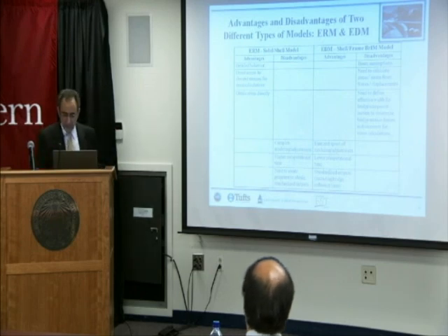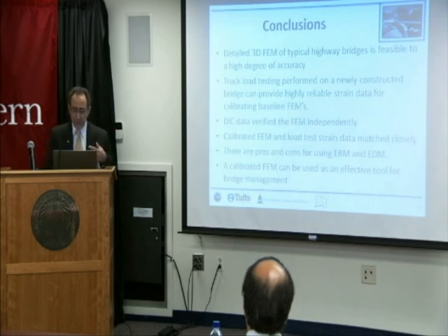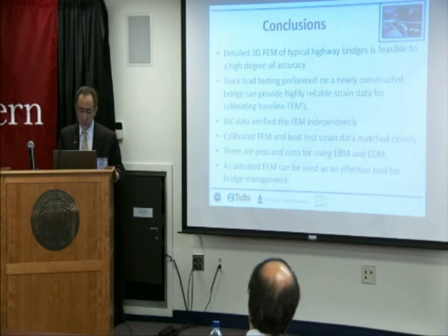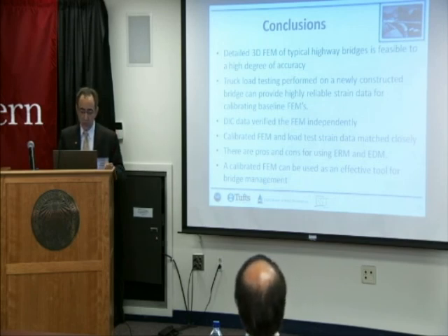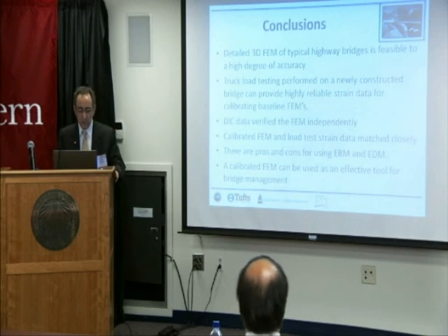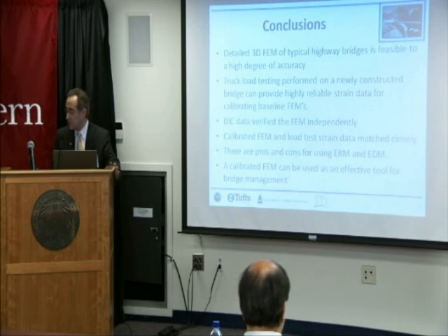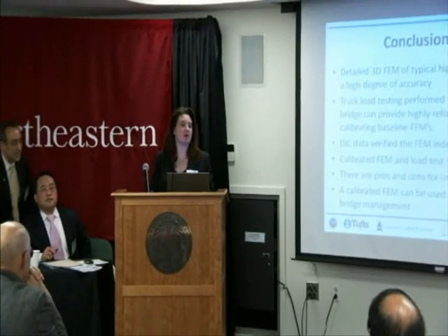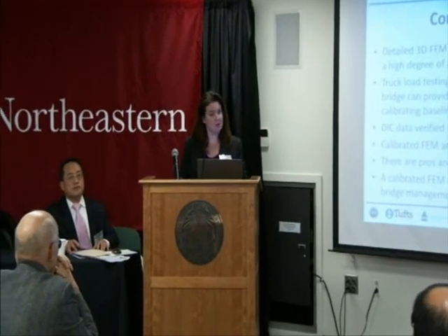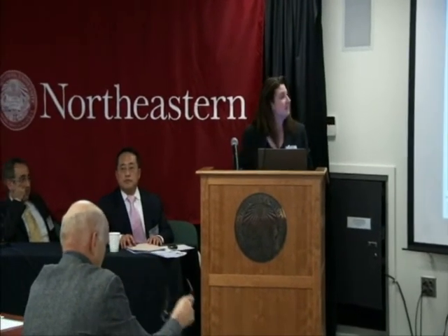So in the interest of time, I quickly say that we were able to update two 3D finite element models with similar results, use them for load rating, use digital image correlation for independent displacement measurements, and calibrate the models. There are pluses and minuses in using different types of models, and the updated models can be used for load rating and bridge management. Our actual presenter on this project is Brian Brenner of FST, so I'm him right now.